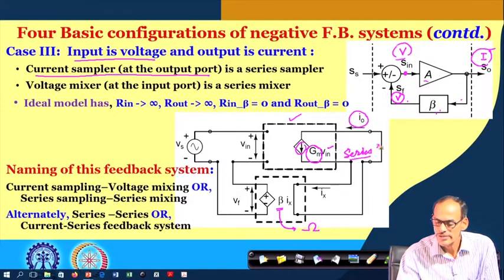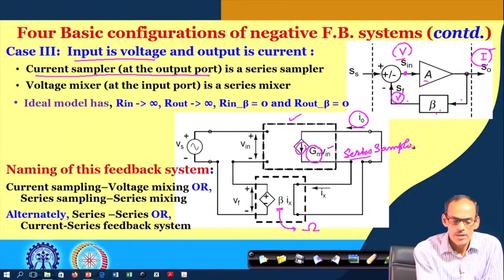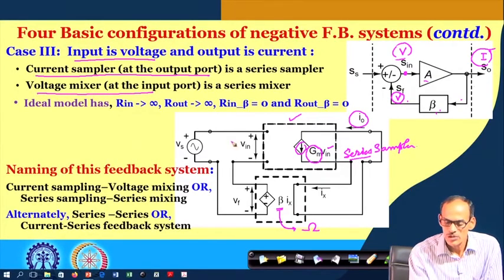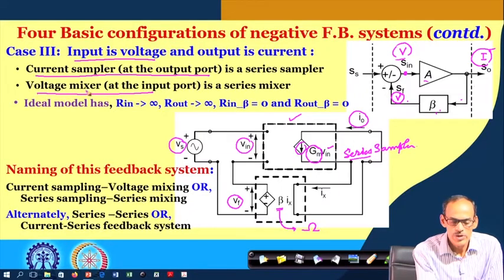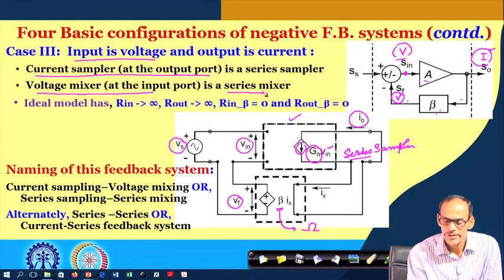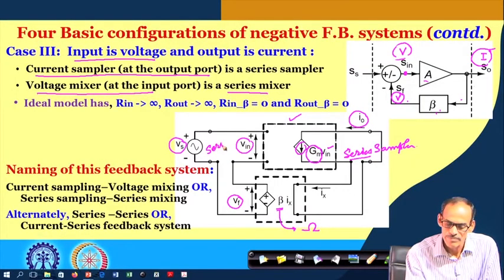So, series sampler. And on the other hand, at the input port we are mixing two voltages Vf and Vs to generate this Vin, and since we are mixing voltage, they are getting mixed by the series connection. So, mixer is series. So, series mixer.